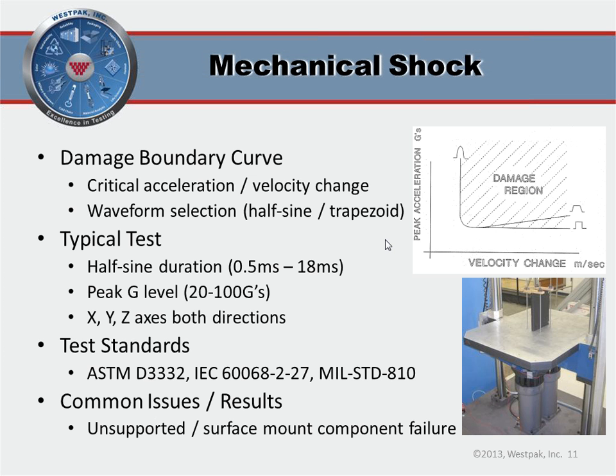We delve into this topic very deeply when we talk about shock response spectrum analysis, or SRS, which we'll be doing in upcoming seminars. So the waveform is very important when we actually do mechanical shock testing, both the shape of the wave, and its peak and its duration. So typical test procedures use what's called a half sine pulse. It's half of a sine wave.